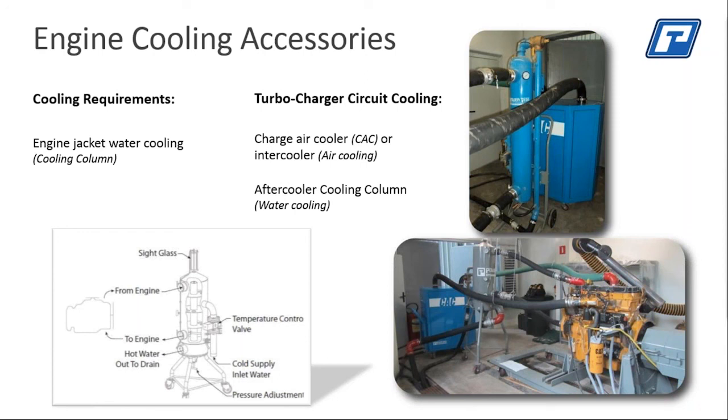I've run into this with a lot of customers that have not bought charge air coolers. Their customers may be a mine, etc., and they require testing directly to the specs of the manufacturer. So if you decide not to do either charge air cooling or aftercooling, understand that you may not be able to reach the capacity of the engine in power and performance.